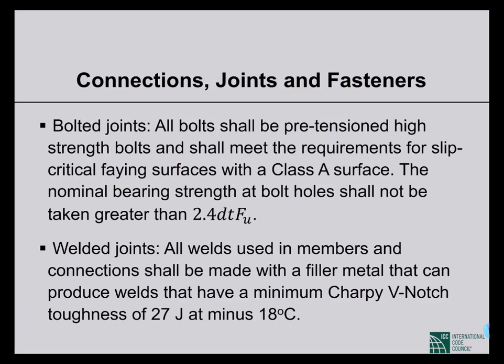And I think I should mention another thing which I possibly didn't include in these slides. It's pre-qualified connections. The seismic provision mentions pre-qualified connections. That is, we can connect beams and columns in many different ways, but some of the details are already pre-qualified. They are tested. So there are manuals for these types of pre-qualified connections.